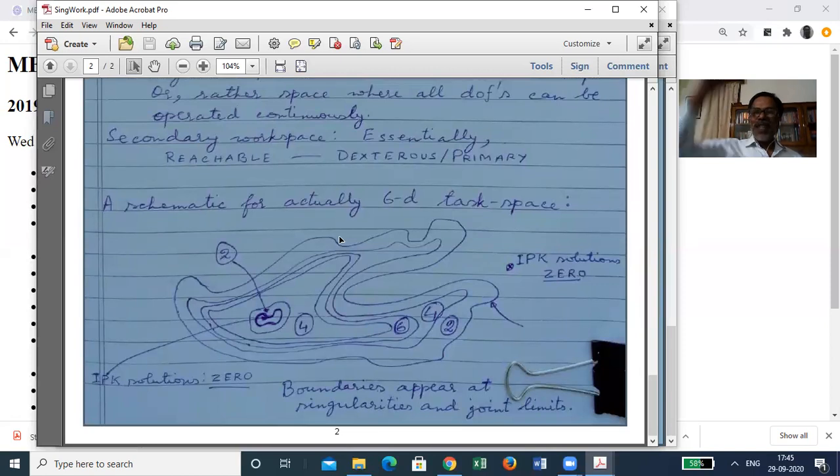But if I extend my arm completely, then I would be reaching a location where I cannot reach in any other manner, right? So at all the points on the boundary, that is at all the extreme reach points, there is a single configuration of the inverse position kinematics.